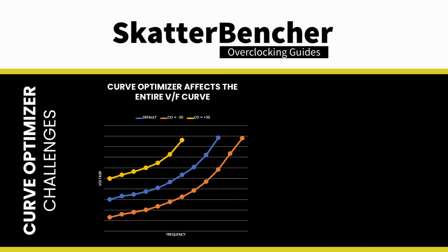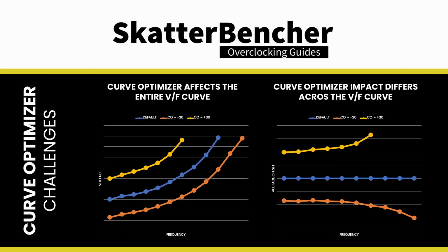Curve optimizer impacts the entire voltage frequency curve, so it affects stability across the entire range of operating frequencies, from 600 to 6000 MHz. The same curve optimizer value also impacts differently across the curve. If you're lucky, your CPU's undervolt margin matches how curve optimizer offsets the voltage. In that case, you'll quite easily get some performance gains. But if the margin of your CPU is somewhere less than in other places, then your curve optimization route or journey can be quite tricky.